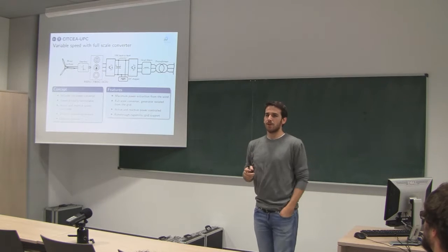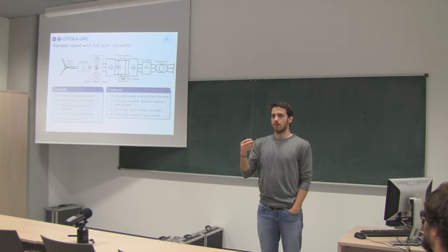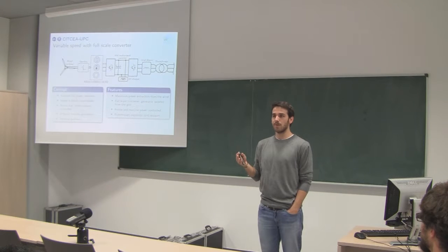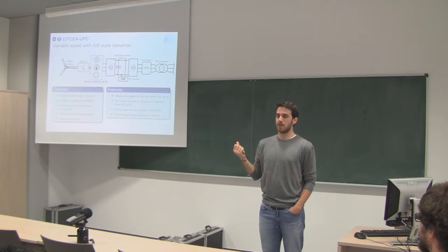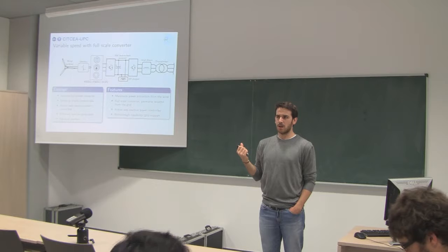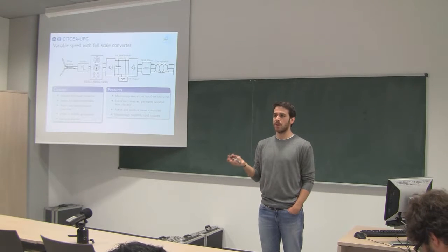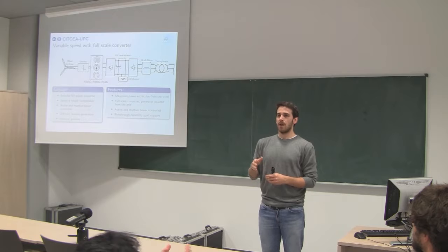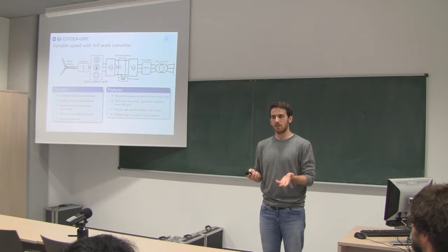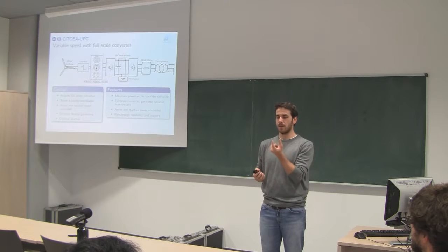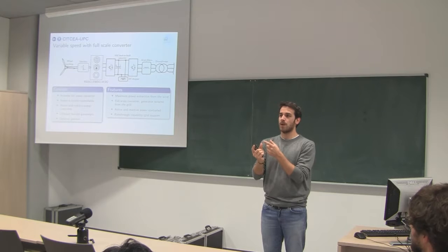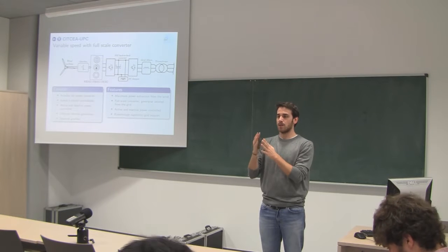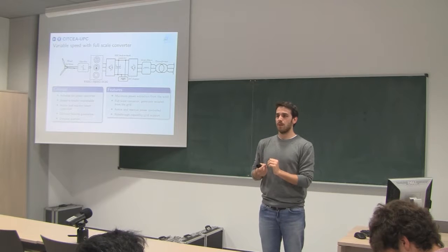Well, I would say that for the onshore industry, the doubly fed was so extended, and everybody was installing doubly fed induction generators, or I mean Type 3 wind turbines. I think that only Enercon, and some other people, have permanent magnet synchronous generator based machines. Every manufacturer has different topologies and proposals. I think most of the manufacturers are going for 3-bladed, and then you also have variations on the gearbox. Some people are installing a multiple stage gearbox. Other people are installing a single stage gearbox with medium speed generators.